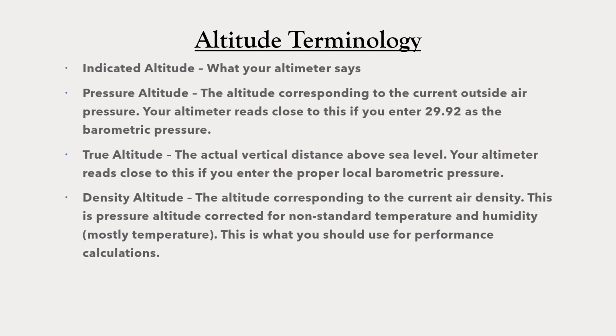So knowing the density altitude helps you if you're looking up performance numbers where the performance number changes with altitude. You should use your current density altitude when you look up in those tables.